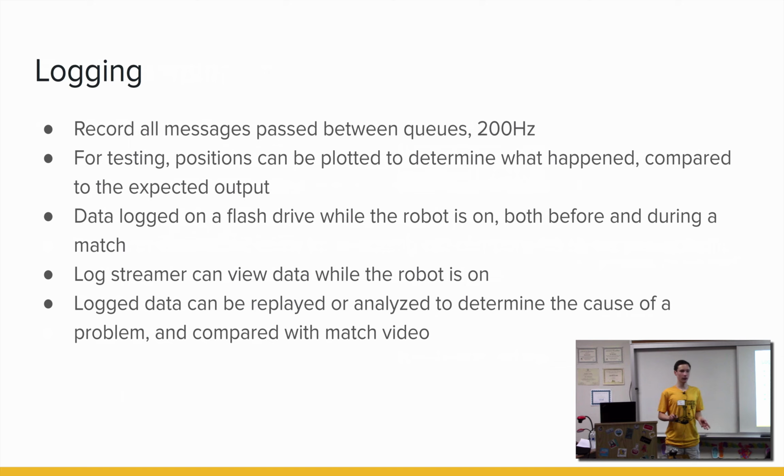So for example, let's say we want to test just the control system itself, and we're moving an elevator from one height to another. We'll make sure that it's moving smoothly, which might involve ramping up the voltage a bit slowly, and then toward the end decreasing the voltage so we don't overshoot the target. And so we can run those tests to see how those systems behave.